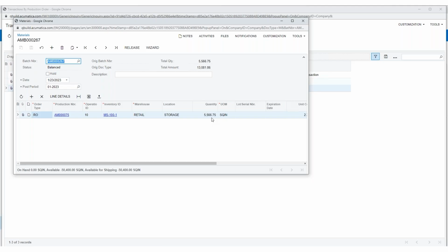So it is taking the true area of the parts, summing them together, and multiplying the scrap or the skeleton area and allocating a percentage of that skeleton area to that true area. The calculation that we do is based off of part ratios, so larger parts will get a larger percentage of scrap, whereas smaller parts consume a smaller percentage of the scrap.